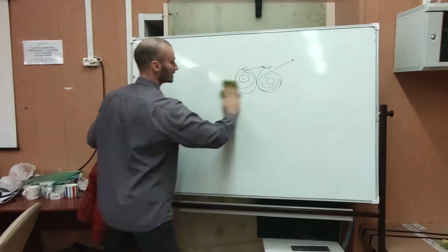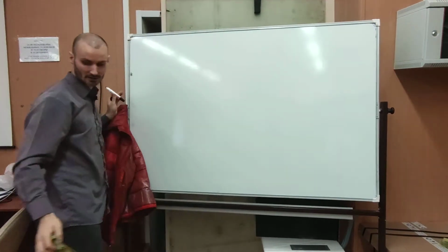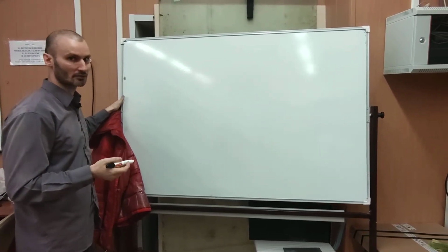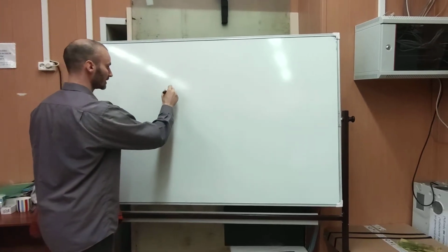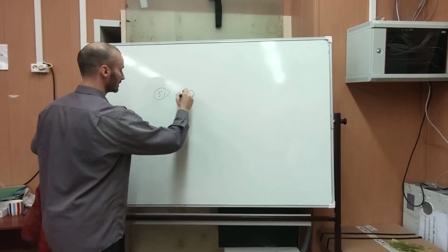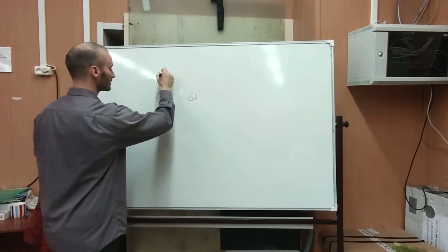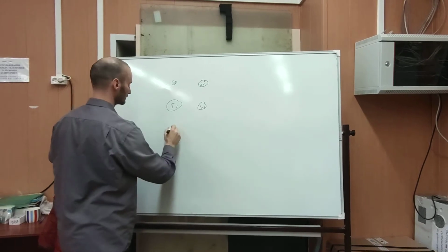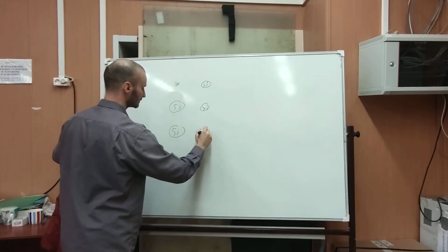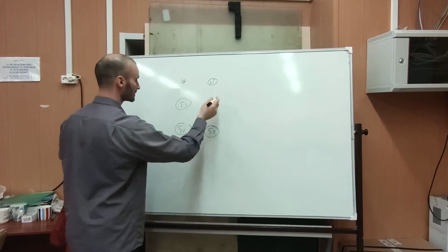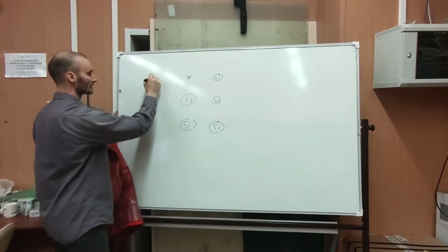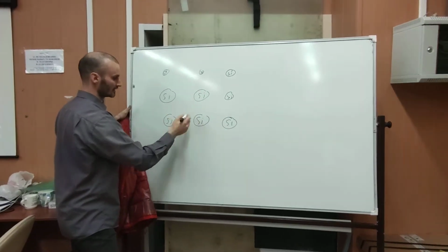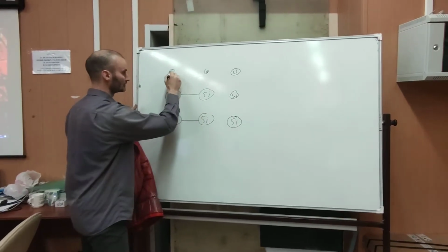Okay, so there are two other ways to make a semiconductor conduct: to dope it with p-type doping or n-type doping. So we have silicon atoms, and each silicon atom has 4 valence electrons on its outer layer. We will draw a 2D representation of a crystal, but actually a silicon crystal is 3D and it's not connected the way we draw it on the board. We're just making life simpler.